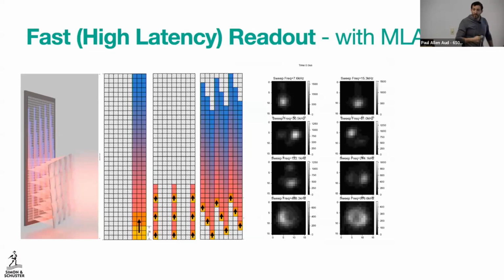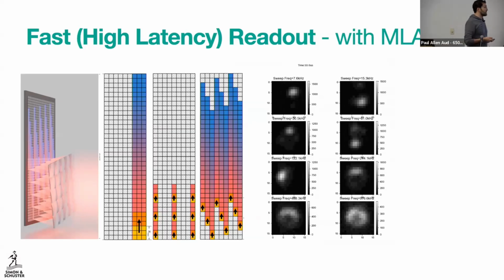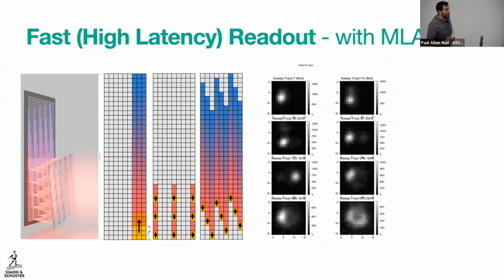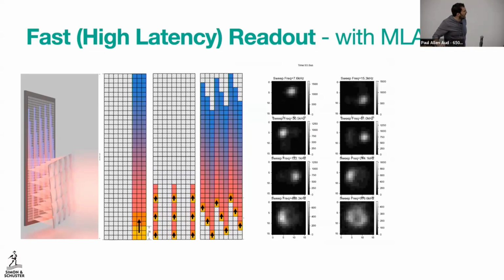And so as you do your readout at, say, 5 megahertz, you get 5 million frames per second from an EMCCD. And so this is just looking at an AOM as the beam moves around in space. But you can now start to imagine using this for high latency, admittedly, but very high speed readout of atom arrays. But then we also wondered, is there a way we could make really high speed spatial light modulators using micro lens arrays?